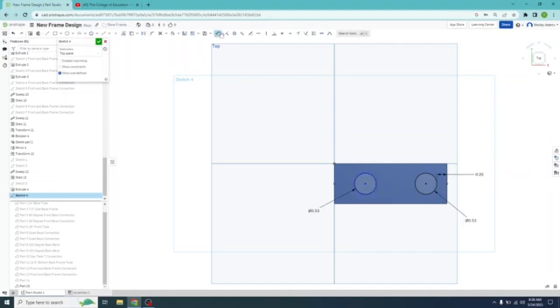Same thing, opposite side, we still have the dimension tool activated, left click on the side, and 0.25. That gives us the dimensions distance apart. So let's left click on that and just find out how far apart are those. So that's good enough, because we're going to need another hole that goes through the center here.